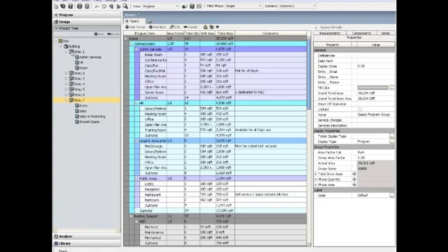Here we can see that the current program contains 7 stories worth of apartments in a building with a footprint of 6,000 square feet. To compare this with a taller, thinner building, I could rerun the Generate Stacking script with 4,000 square feet per story and assign it to scenario 2. For now, we'll just proceed with the analysis. Let's see what this looks like in the story view.